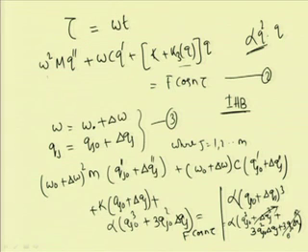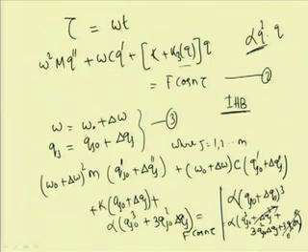Now we already know that if q j 0 is the present state of this system, then it will satisfy the governing equation, or equation 2, as omega 0 and q j 0 are the current state of the system. If it is satisfying this equation, then this term, omega 0 squared m into q j double dash plus omega 0 c into q j dash plus k into q j 0 plus alpha into q j 0 cubed, will be equal to f cos n tau.